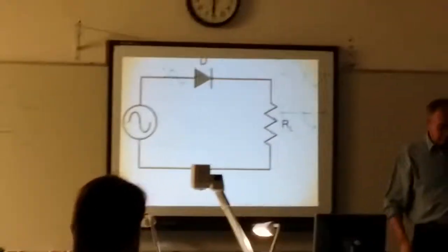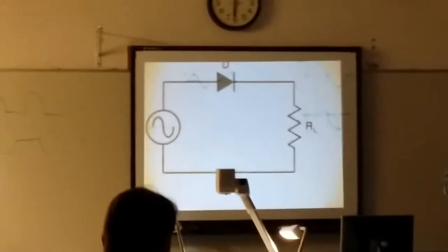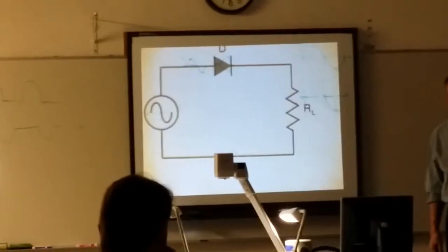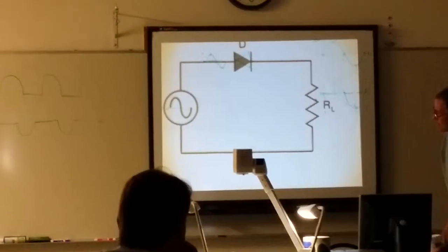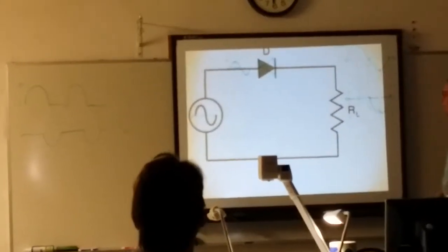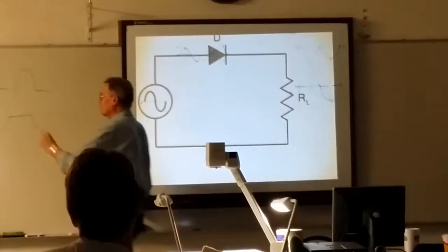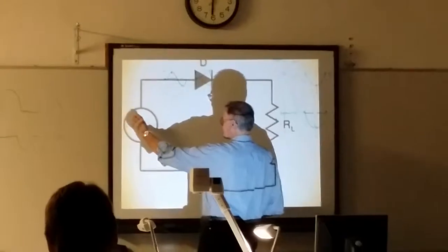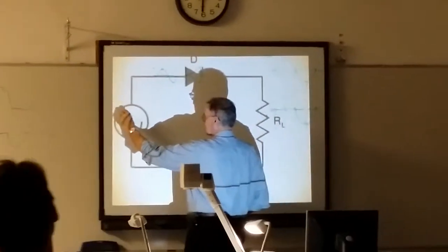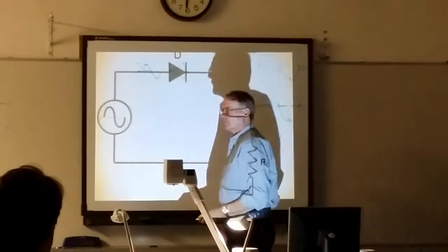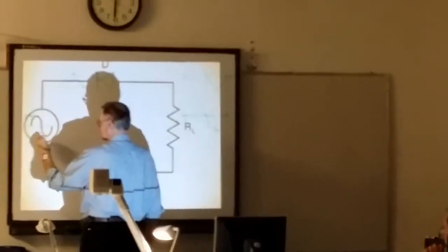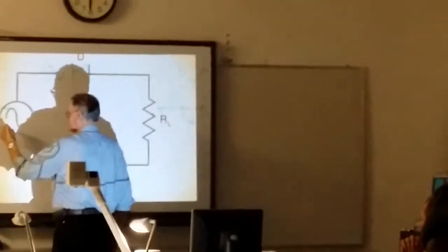But that's all that circuit can do. It's a half-wave rectifier, and it has very little application, but it does have some. The application is for charging a battery. It's a cheap way to charge a battery. Let's say you have a 12-volt battery. And remember we did this last week? Let's make this a 24-volt peak, and this is negative 24. So the peak-to-peak voltage is 48.